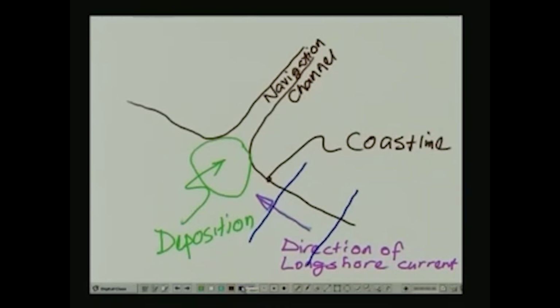So we install a series of groins, so-called groins, to control the longshore current and the deposition near the mouth of the navigation channel.